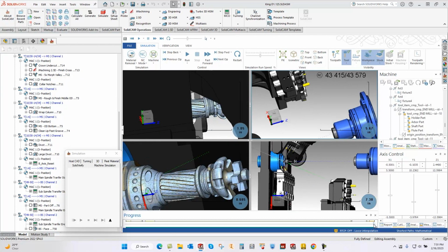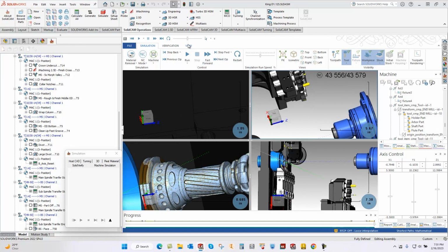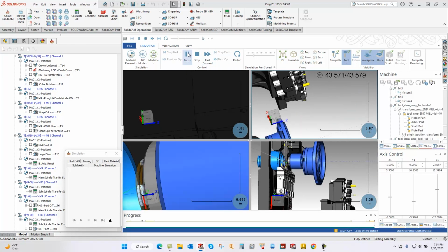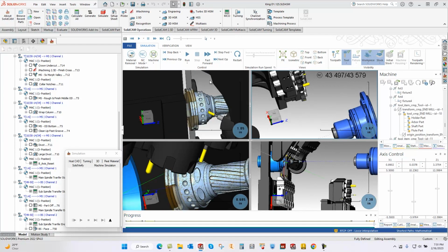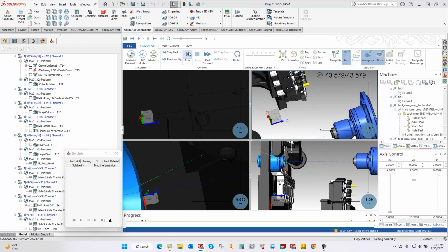I'll do that again. I'll pull it back a little bit, go to the next stop, and we'll slow it down a little bit and play. Cut. Did you see that? Just one more time. You'll see it do a cutoff after it grabs it with the sub spindle. Look at the lower right-hand corner, cut off, and pull it back, and you're ready for another part. Go drop off this one and feed that bar out and continue on.